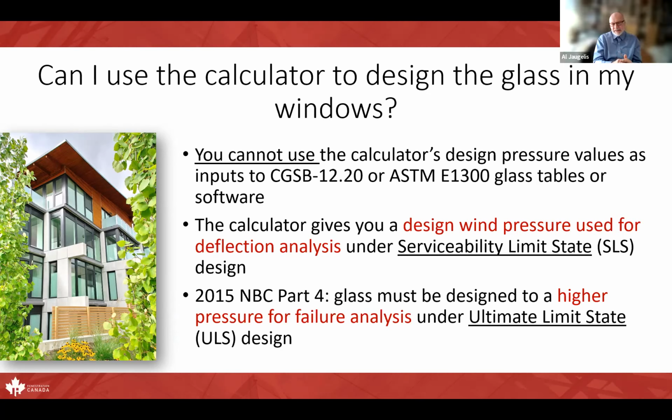Right. So basically, don't assume that you can take your design pressure value from the calculator and go directly to a glass design calculation. The paper that's going to be published will provide guidance on how you would factor the load to use it with the appropriate calculation method. But we're not at a point yet where we can provide that guidance. You cannot yet go from the calculator to the glass in one step.